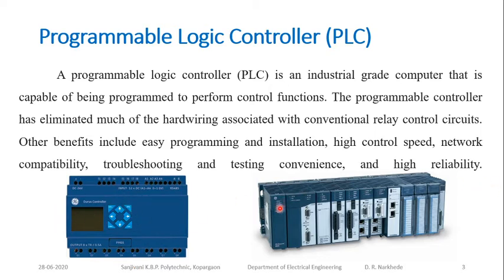In case of modular PLC, your power supply is different, the processor is a different part, the communication module is different, and it has expandable slots to which you can connect a number of input output devices. So this type of PLC is used for a large number of applications, okay, where the input output requirement is large.